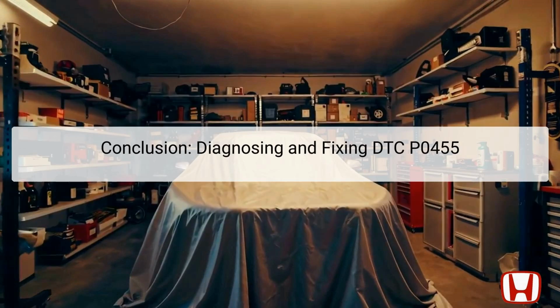In conclusion, DTC P0455 indicates a large leak in the EVAP system that can be caused by several factors, including loose or damaged fuel fill caps, cracked vapor lines, or faulty valves. Following a systematic troubleshooting process as outlined ensures a thorough diagnosis, from simple fixes like tightening the fuel cap to replacing major components like the EVAP canister or vapor lines.